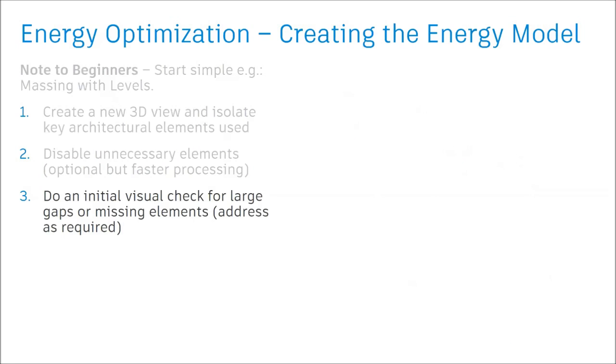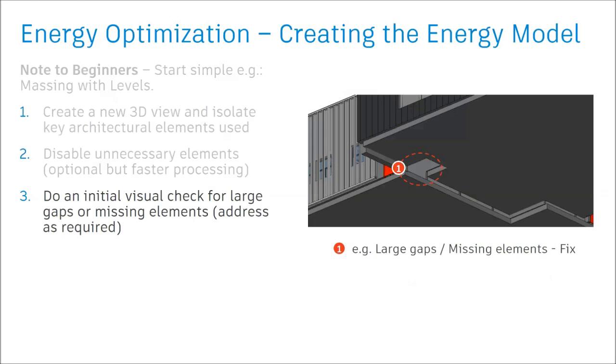Remember, I talked about this the last day: this algorithm expects there to be reasonable small gaps and overlaps in the model. It's highly tolerant of that. But when they get above a certain size, really to the point where there's something serious missing in the physical model, you need to address them, and there are different ways to do that.